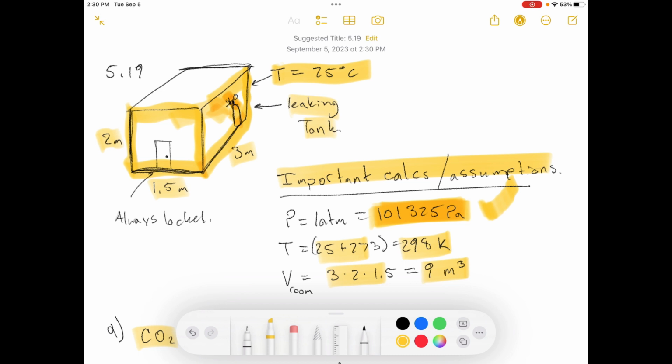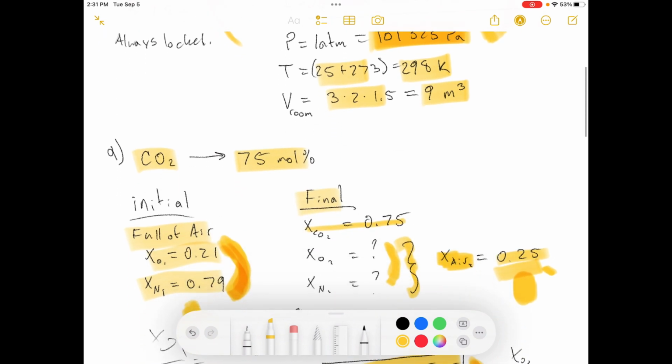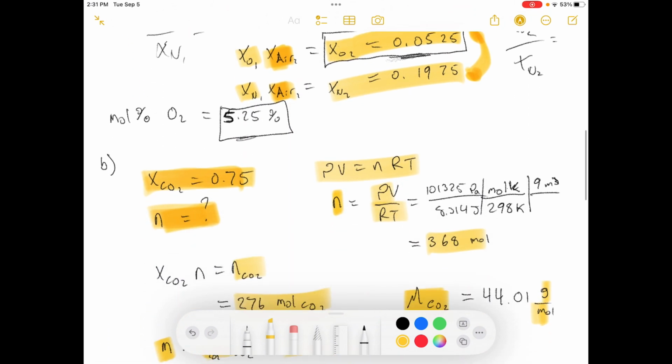The room isn't sealed, so the CO2 that comes into this room is displacing some of the air. Well, if you assume that the carbon dioxide and the air mix together in here, and the room is not sealed, some of that carbon dioxide is going to leak out of the room over time, right? So you're not going to reach the lethal limit immediately, because some of that CO2 is going to leak out along with the air. It's only when the amount of CO2 leaking out of the tank is greater than the amount of CO2 that's leaving the room that you're going to start building concentration inside of this room, and then as that concentration builds over time, eventually you reach the lethal limit. So that's why more mass from the tank would have to leave the room.